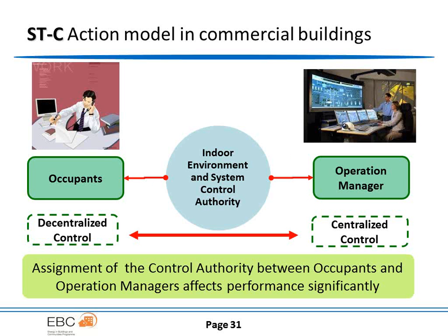We're also trying to look at commercial buildings. I think we're talking about central systems, VAV systems, and now going more to these localized systems like VRF and fan coil systems, which provide better zoning control. So if you don't need it, you just turn it off.